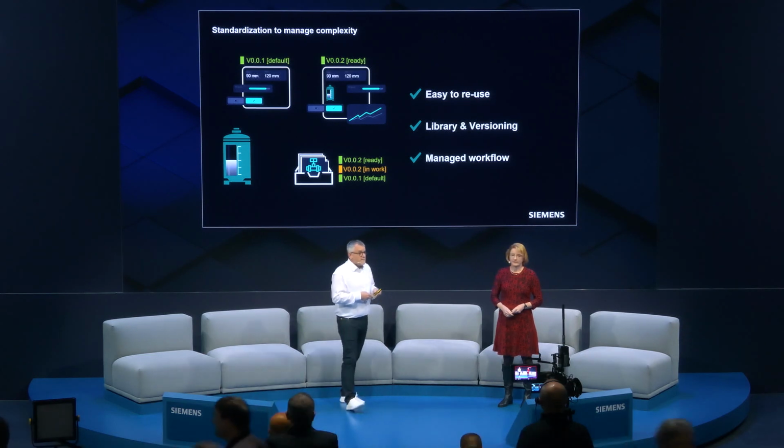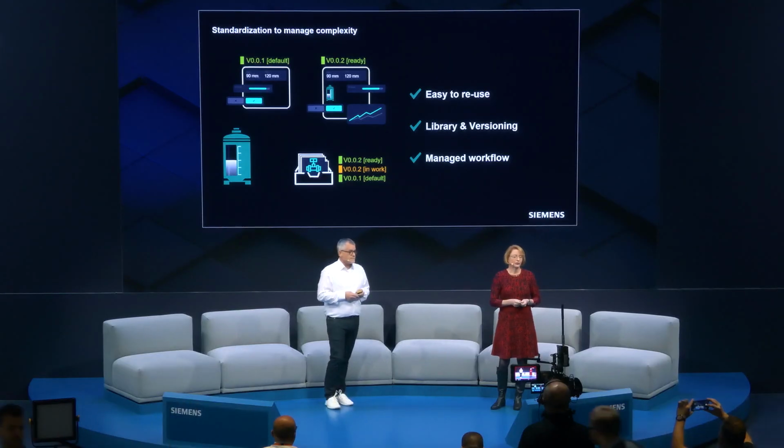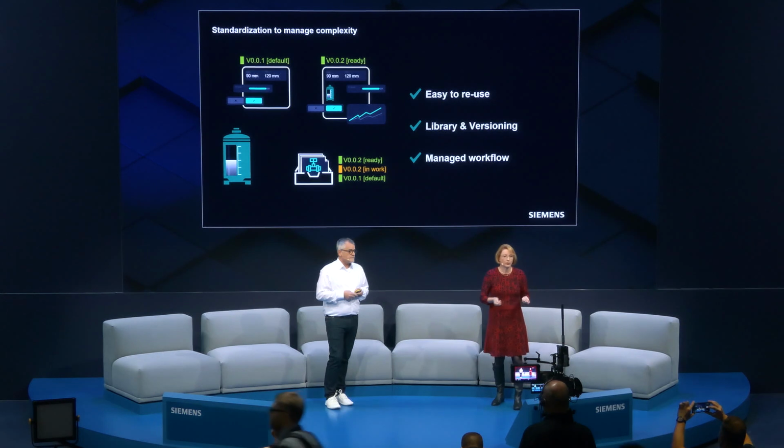And finally, with version 18, faceplates can be nested within faceplates. The next step of reducing complexity is to manage other elements, for example global scripts, graphics, scalable vector graphics, or our dynamic SVGs. They are all managed in our TIA library, including workflow and versioning. So they can be used in other faceplates or in a screen. Libraries are really a very efficient way to manage your standardized HMI components.